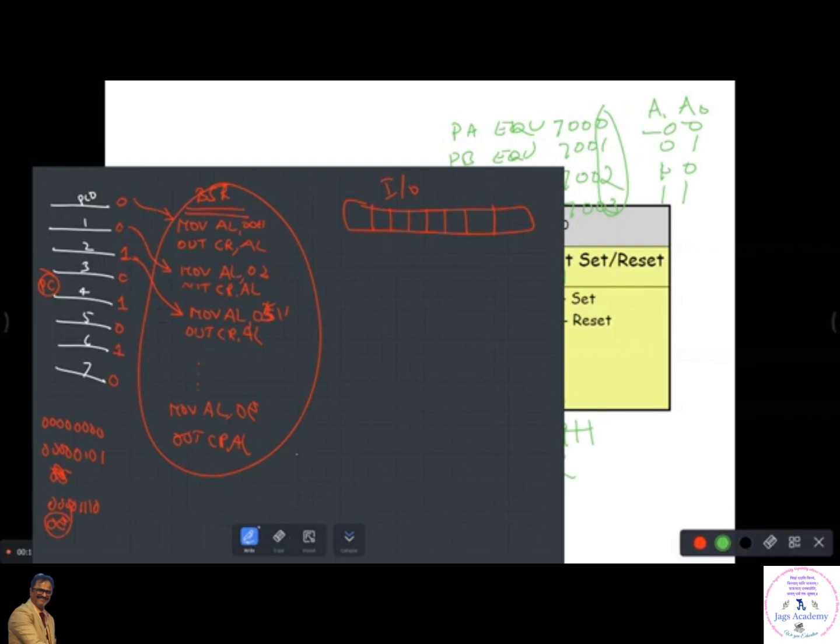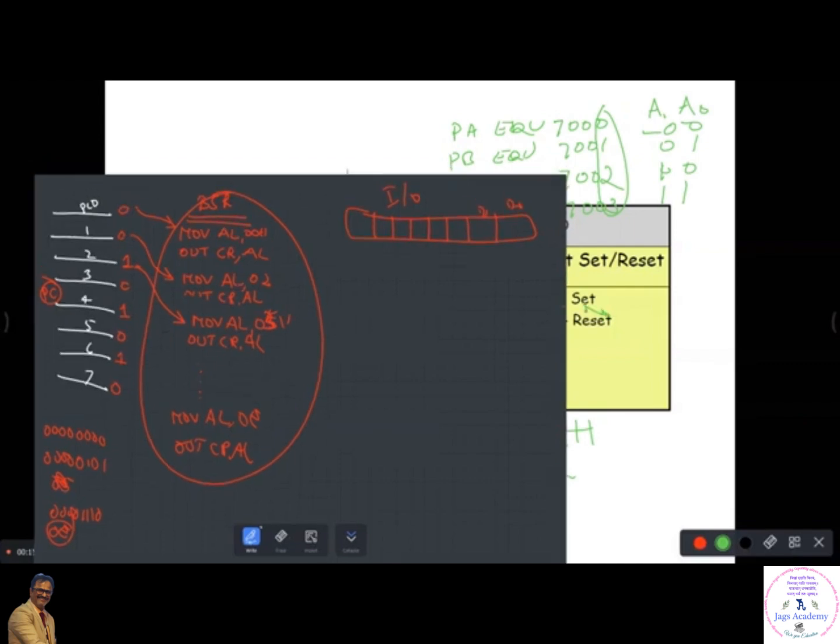Now in IO mode, first you have to configure the port. What is the port configuration? First you have to get a control word for the configuration of ports. So here we are using port C in the output mode, right? Yes. Okay. Now which is the corresponding port C control word bit here? Come on, look at your mobile now. Which one is that? Tell me. Come on, come on. First, D0. D0 is port C lower. Output, right? Output means 0.